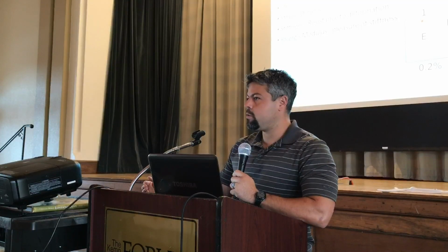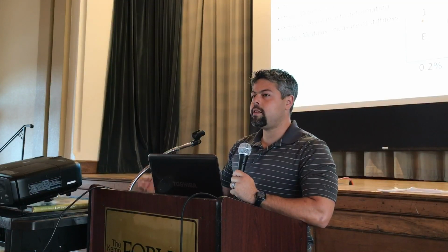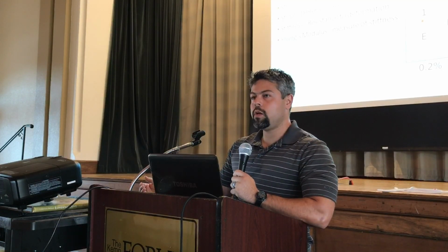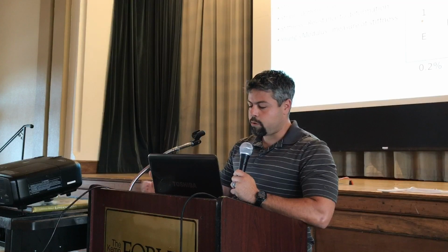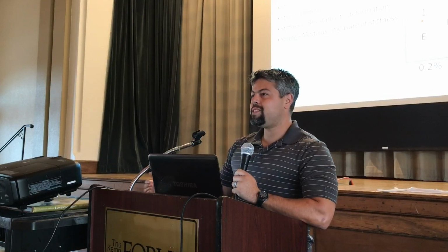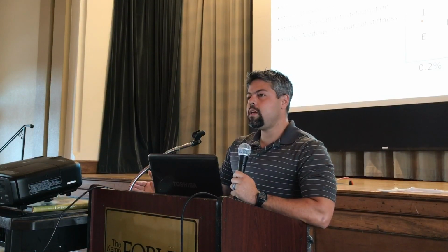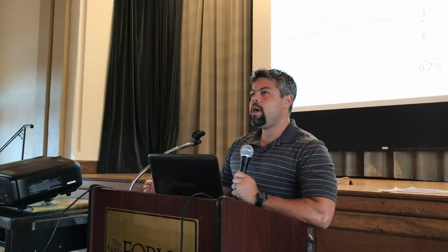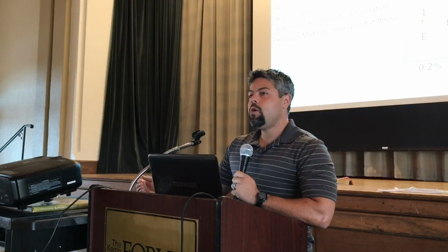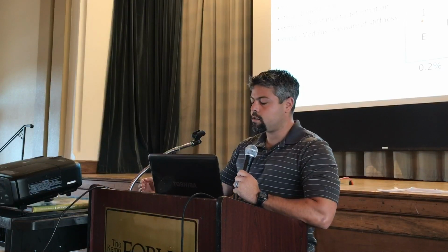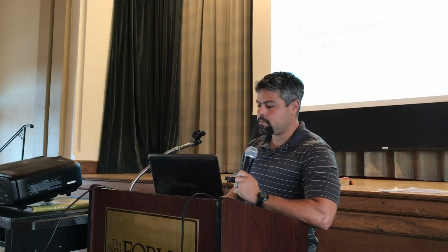We see that with arthroplasty, which we'll go into later, in that the connective tissue, which is now the structure, becomes stronger than the bone, then the bone becomes a failure component. When we talk about stiffness, it's its resistance to deformation. The higher stress resists further strain. So immediately we think, okay, stiffness is a good thing. It's measured by Young's modulus. So when you look at this research, if you increase the stiffness of the tissue, we have increased its ability to transfer force and improved it without necessarily changing its size, which becomes important later.